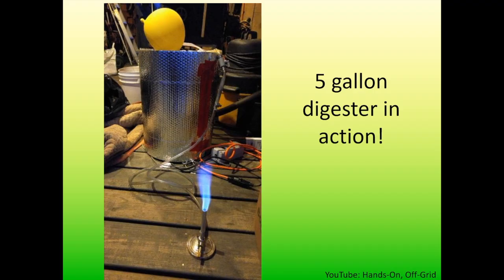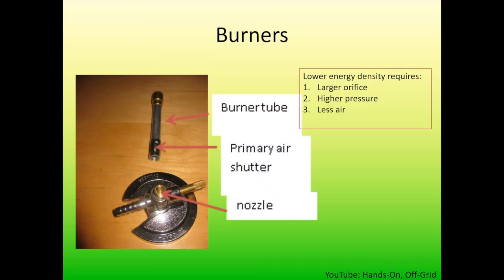The 5-gallon bucket is a great science project for your school. Because there's a lower content of methane in biogas as compared to natural gas or propane, you'll need to modify the burner for optimum flame. This usually means a larger gas orifice and less excess air. Nozzle orifice sizing guidance is also provided in the DIY biogas book. Burners are somewhat forgiving, but engines are not. If you want to run an engine on biogas, you'll probably need to scrub out the impurities.